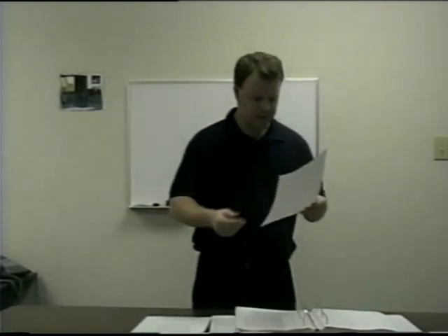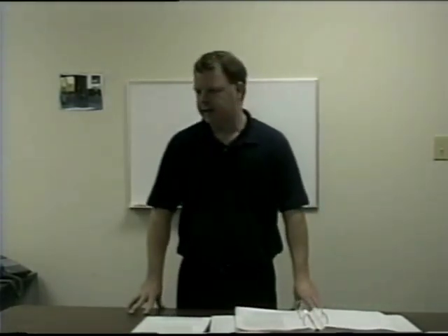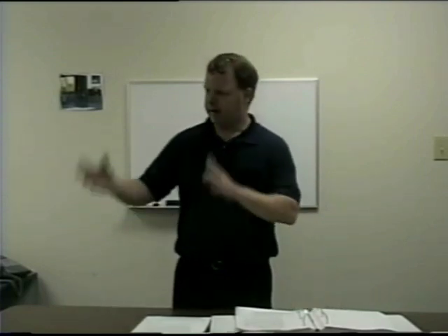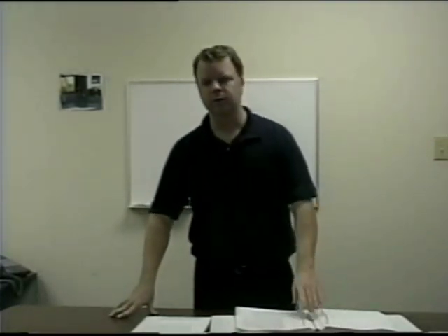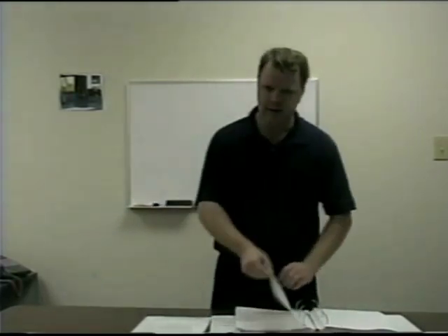Okay? It says, verify asphalt and pitch are not overheated. Check kettle thermometer. You know how many times a roofer shows up on the job and the superintendent just assumes, well, he's a roofing specialist. He knows how to roof. I don't know much about roofing. I better just let him do his job. Well, that's not the job. That's not the role of superintendent, is just to let them do the job. We've got to look over their shoulder and make sure that they're doing it right. Check the temperature on the kettle. Mark it off on the check sheet. All this stuff.